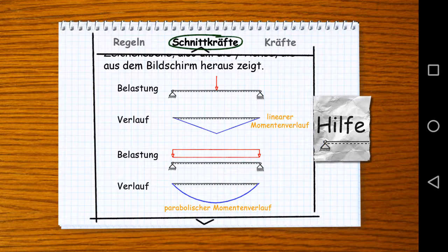So when you have a negative curvature, the tension side is downward. So you can actually imagine that the lower line of the beam is going to be stressed a little bit more than the upper one, or we can actually say that the upper one is going to be under compression while the lower one is going to be under tension. So the tension side is downwards.